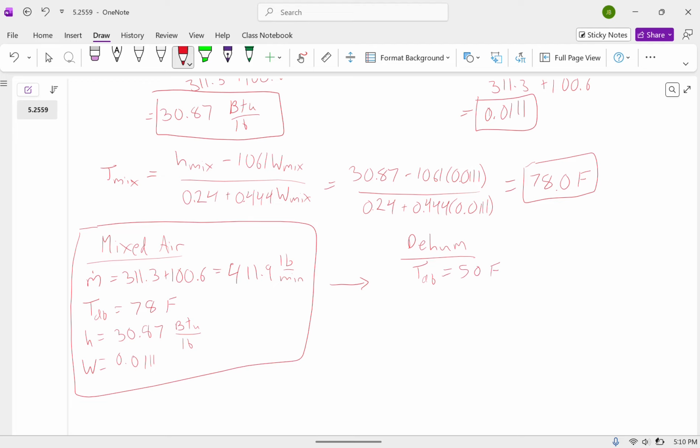at the saturation curve. But we'll just say it's a little bit lower. We'll say about 95% for this example, because we can't be right on the saturation curve. So we'll take 95% humidity as our second point, and from those two pieces of information, with the 50 degree Fahrenheit and 95% humidity, we can determine the rest of our state. And so we'll just do that using our Psychrometrics calculator on Heatwise and populate the rest of the data.